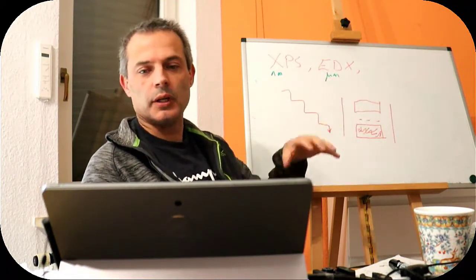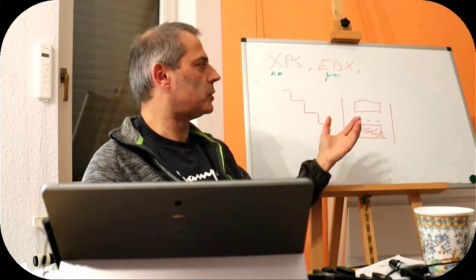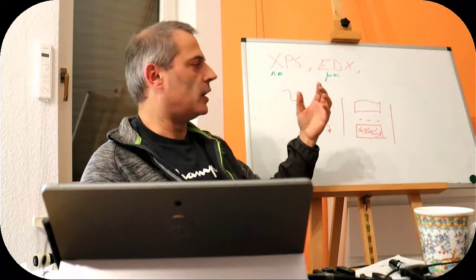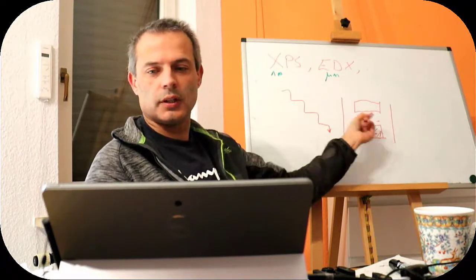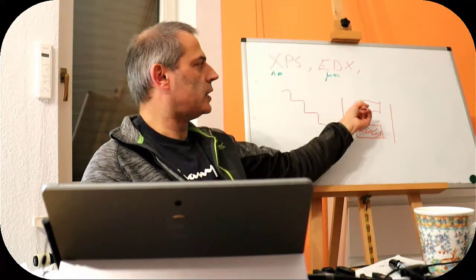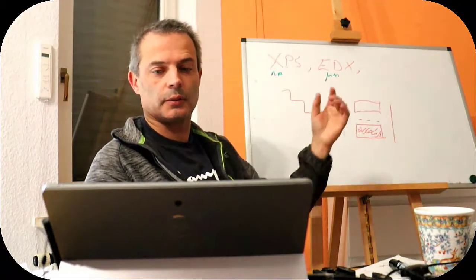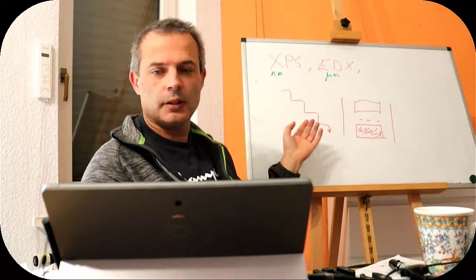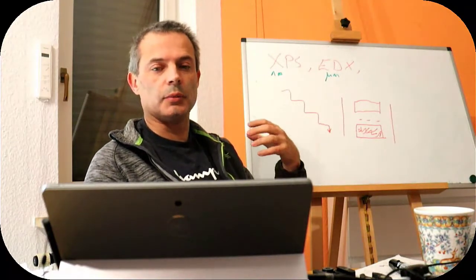That either gives us a P or an N-doped semiconductor, and that means that we can either conduct with holes in this band down here, or with electrons in the normal conduction band. The reason that I've got it here is that we're going to hit it with a light, and the light is going to excite some electrons.